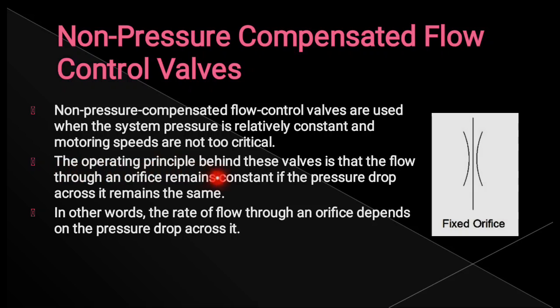The operating principle behind the valve is that the flow through an orifice remains constant if the pressure drop across it remains the same. As I explained, it is just an orifice. By reducing the opening of the valve, we form an orifice.